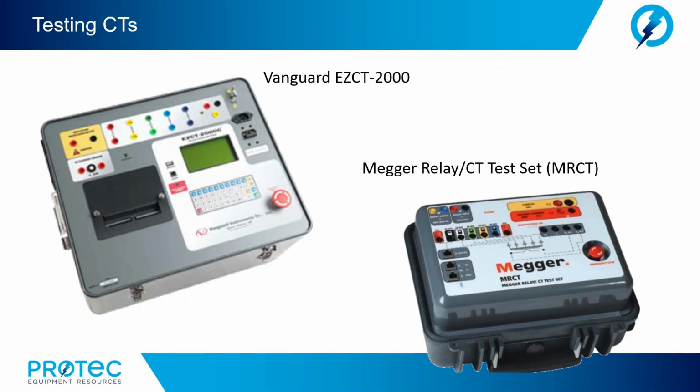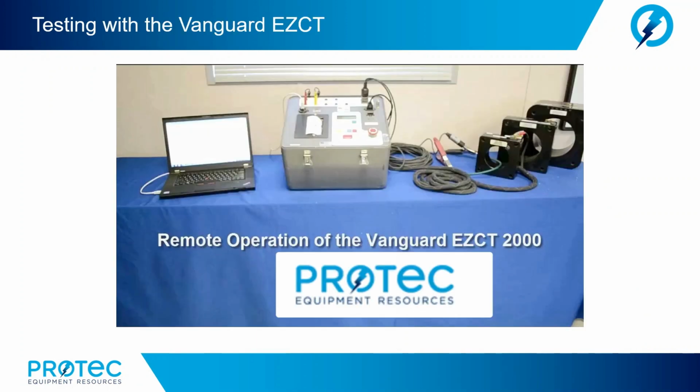Now, when testing CTs or any other device, it is important that you understand the test set that you are using. Now, two commonly used test set brands are the Vanguard and the Megger test sets, as seen in this slide here. Now, if you are using the Vanguard test set, you will need to program the maximum voltage you wish to apply to the CT secondary and maximum current that you wish to measure. The Vanguard tests can be operated either manually or using their remote software. Let's just take a quick demonstration of how the remote software would work.